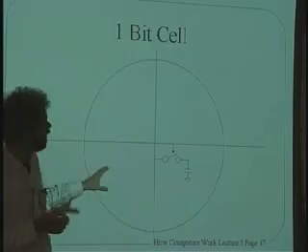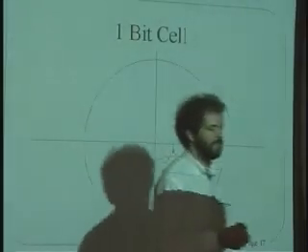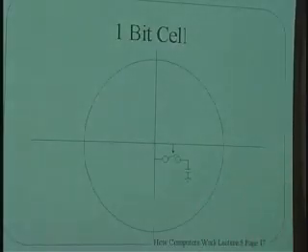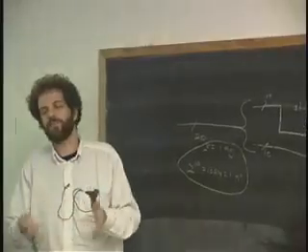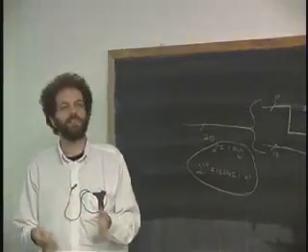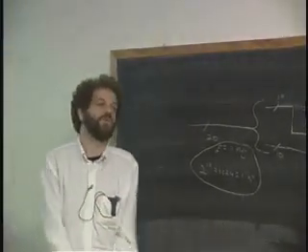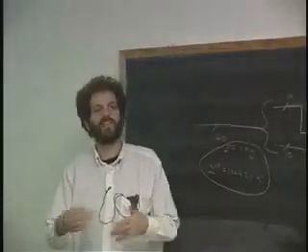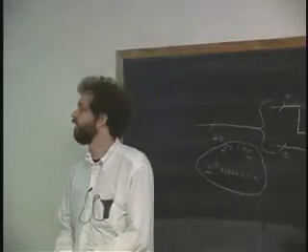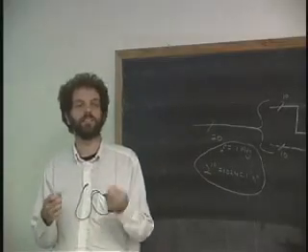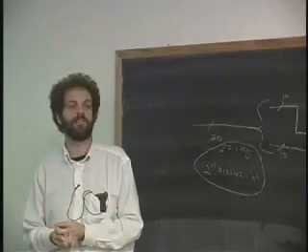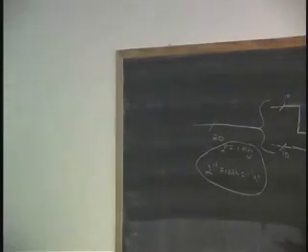And the guarantee that they give, usually with these chips, is that the storage on these little plates, which serve as little bathtubs to hold charge, is leak-free on the order of a thousandth of a second. Just like if you fill up your tub, even if it's a leaky tub, and you come back a second later, it's not that all the water is going to be gone. It takes an hour for the water to slowly leak down. So with these typical devices, it's on the order of a millisecond, the time constant, but you can depend that the charge will still be there. And we'll talk about what that means.